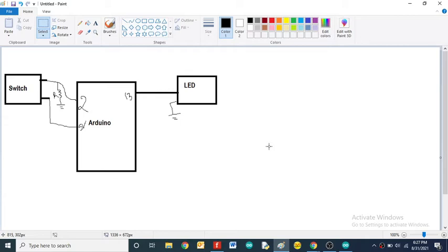First, we have to make the particular pin an input or output, that is the pin status. Second, if the pin is made an input, then we need to read the information from that particular pin, the pin we have made an input. After that, if the connected device is an output, then we have to transfer the information. Here we have both conditions: the output device and the input device.